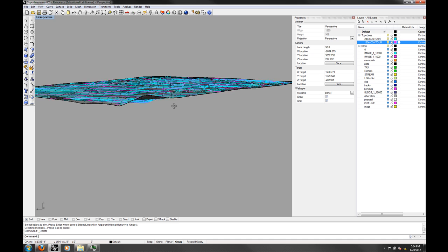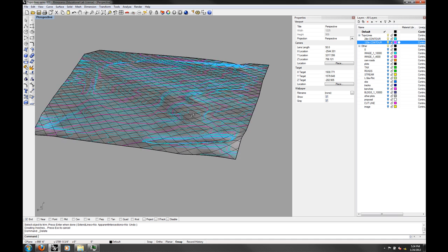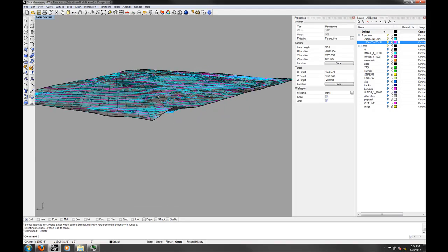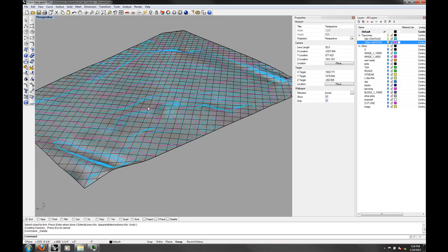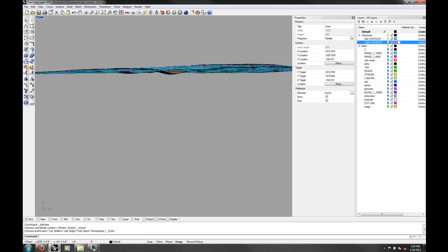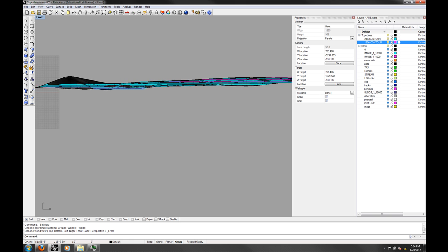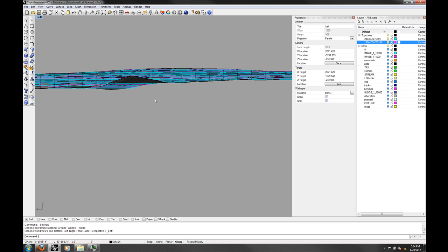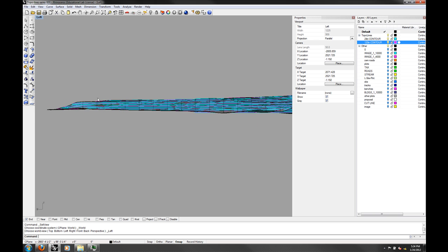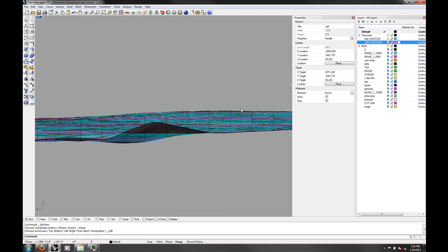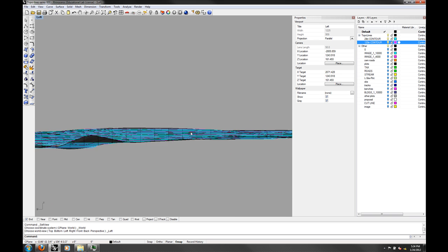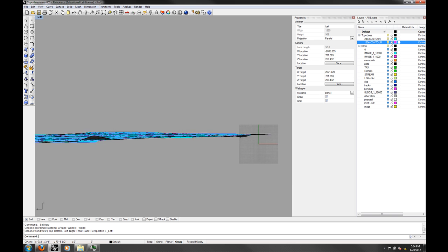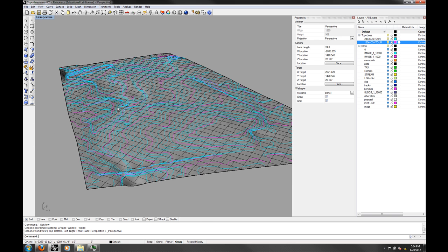So patch is a simple operation, but when you do this kind of thing on your own, the next time you do it, make sure you check it against the contours and make note of anything that seems really off. And that will prevent you from running into any serious problems. But you can see, other than those edge things that I showed, it's fairly close. Boy, that is way off though. Just pay attention to it. It's usually the edges of things. Looks like the very top is maybe a bit off. Again, if you would like to talk about how to get a more accurate version of the site, we can. But for now, this is going to be good enough.